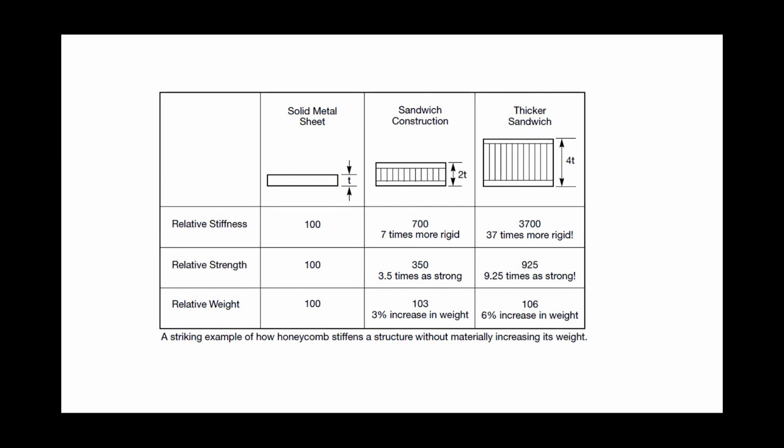These characteristics do not change linearly, but rather in an explicitly non-linear way to our benefit in terms of mass reduction or acceptable mass gain if you use foam as a building block of your composite structure. That's one of the advantages.